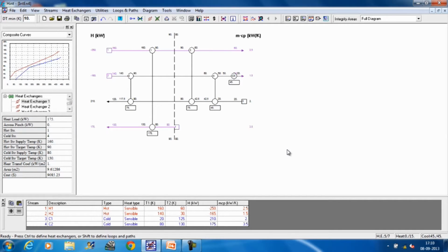From the units targeting, we know that if there is a loop, then it consumes 1 extra heat exchanger per loop, and if the number of heat exchangers are more, then obviously the cost will be more. So, we have to do a trade off between the number of heat exchangers and the TAC. So, we will identify the loops, we will break the loops, and once we break the loops, we will find that it causes delta T minimum violation, and to eliminate that delta T minimum violation, we have to pass the heat from heater to cooler